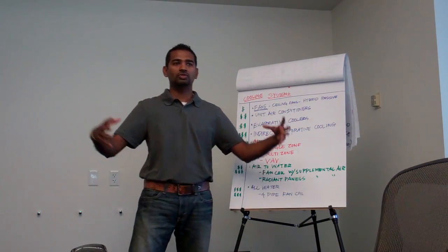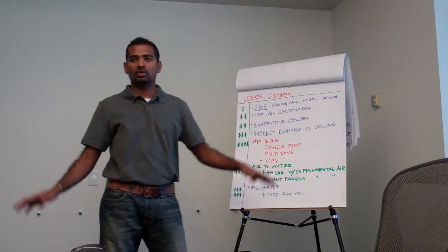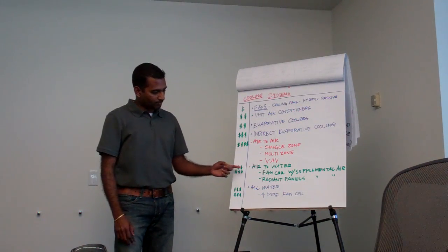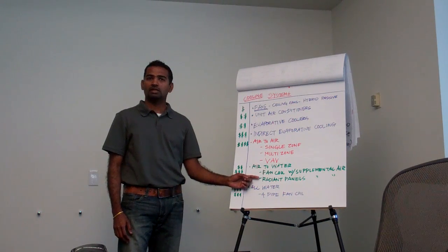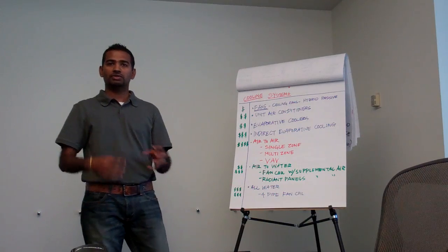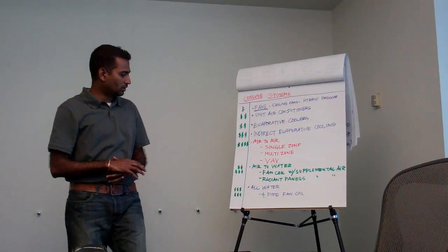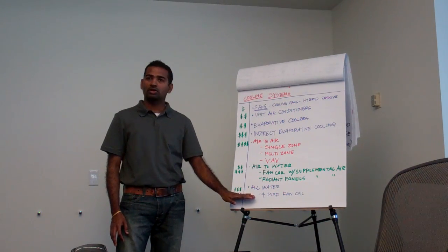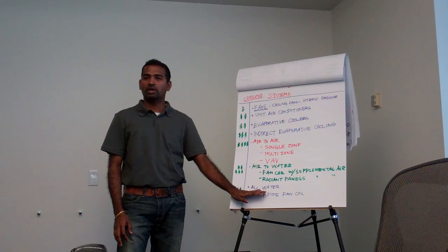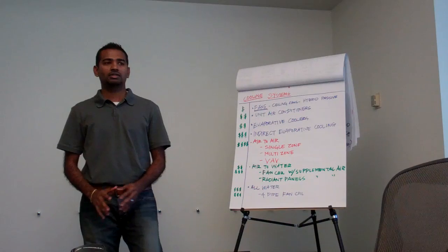So we don't have a huge centralized air handler to take care of all of the classrooms. And then the other common air and water system is the radiant panel system, where you separate the heating and cooling part from the air conditioning part. Then the last one is the all-water system, like the 4-pipe system, and here it's assumed that you take care of air separately.